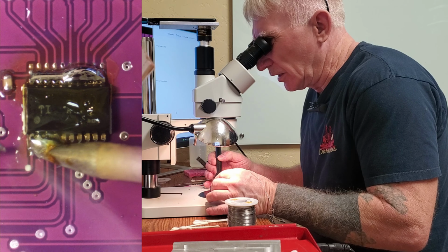And then I'm going to get my tweezers ready. And then I'm going to heat this bad boy up, just like this. Let it sit there, not too long, but it's got to get everything reflowed. And we got to jump to this side. Got our tweezers ready. So we got to get it hot enough that one side stays hot until we reflow the other side.